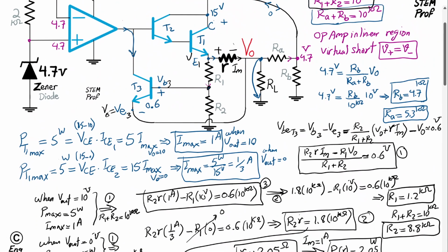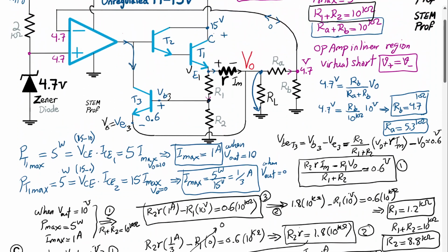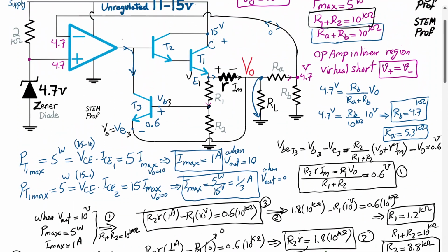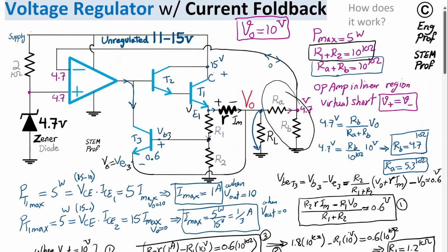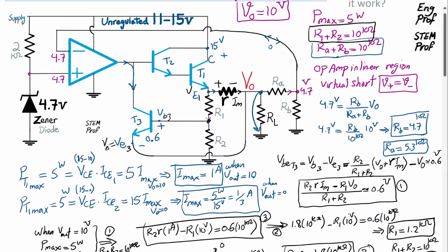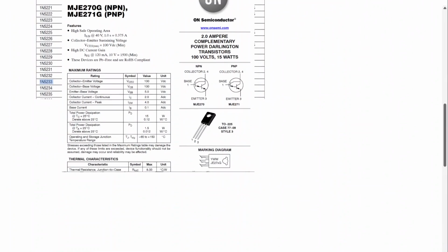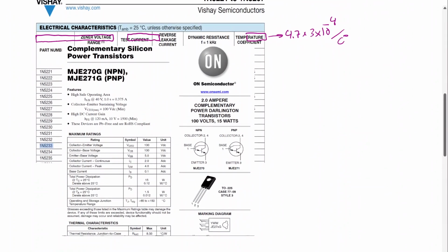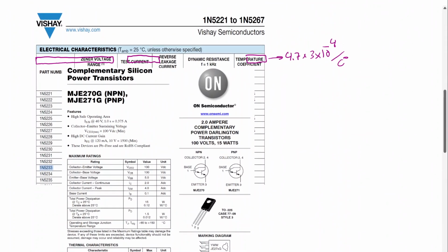So we found the value of this resistor as well, and that's the last component that we needed to figure out, because we found earlier the values of RA and RB, and now we found the values of R1, R2 and resistor R. The NPN transistor is just a nominal transistor with a nominal beta of 100. The PNP one is the one that at least can tolerate Pmax of 5 watt, as we discussed, and one option is from ON Semiconductor, as I showed.